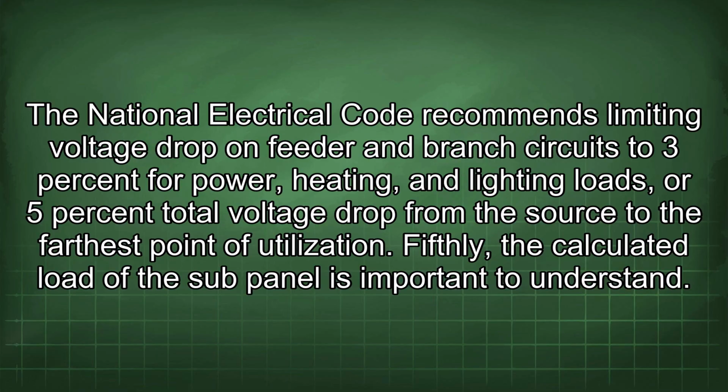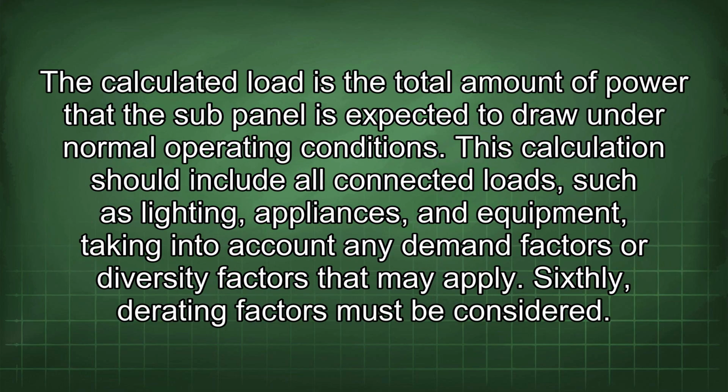Fifthly, the calculated load of the sub-panel is important to understand. The calculated load is the total amount of power that the sub-panel is expected to draw under normal operating conditions. This calculation should include all connected loads, such as lighting, appliances, and equipment, taking into account any demand factors or diversity factors that may apply.